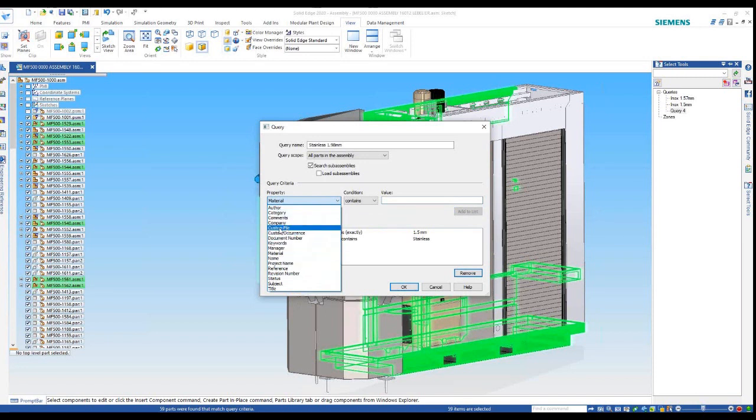And I can get to these using custom file, and then I just simply type material thickness. Now, this has to be set up correctly to expose your part variables as this custom file property, and that you typically set up in your template. 1.98 millimeters.